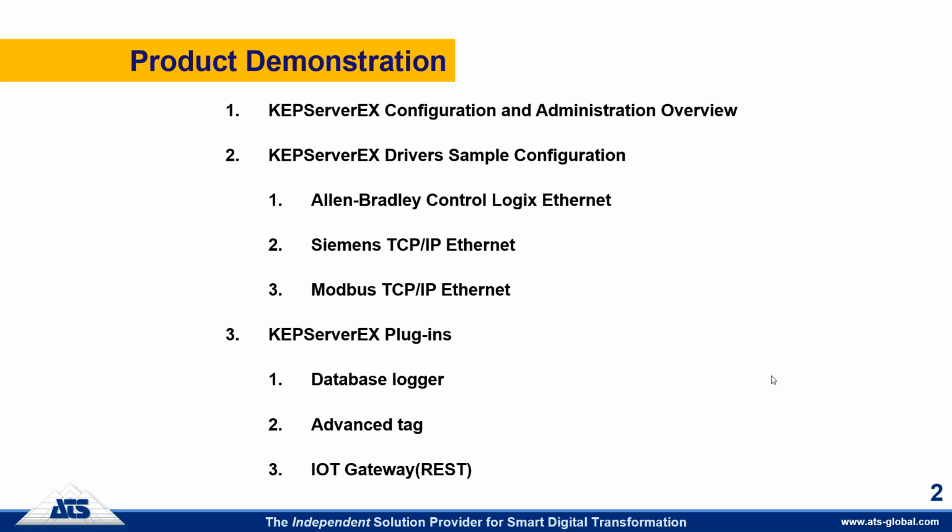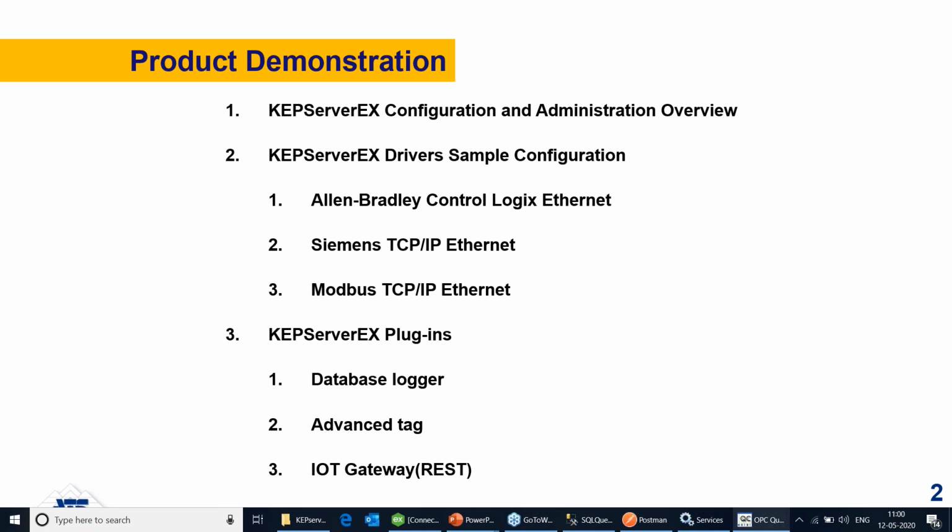For IoT Gateway, we'll go through the configuration and demonstration of the REST protocol. We'll make Kepware a REST server, and we'll use Postman as a REST client. We'll first start with the configuration and administration overview.